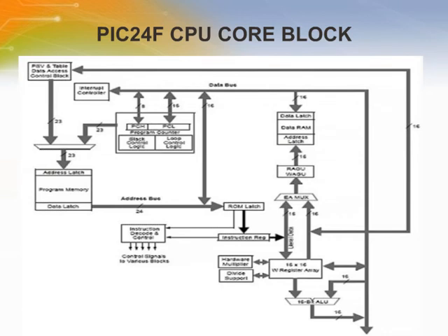The PIC24F CPU incorporates hardware support for both multiplication and division. This includes a dedicated hardware multiplier and support hardware for a 16-bit divisor. The PIC24F arithmetic logic unit is 16 bits wide and is capable of addition, subtraction, bit shifts, and logic operations. Depending on the operation, the ALU may affect the values of the carry, zero, negative, overflow, and digit carry status bits in the status register.